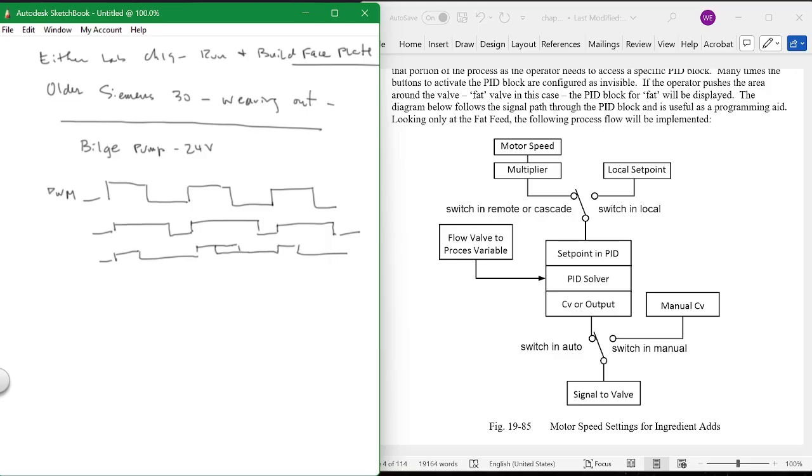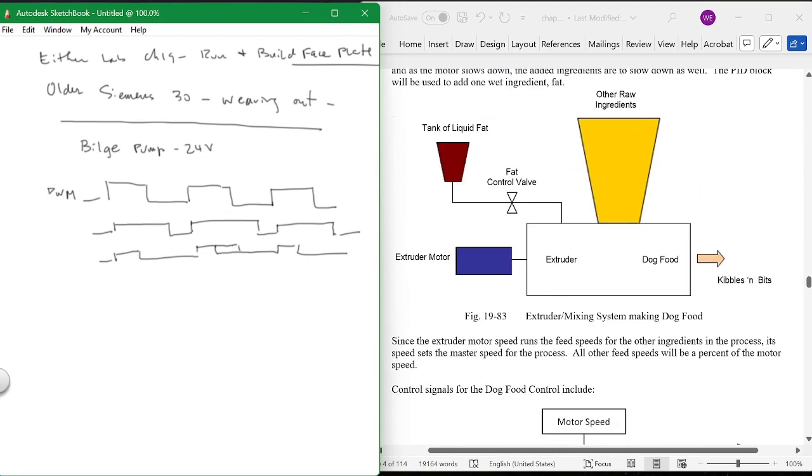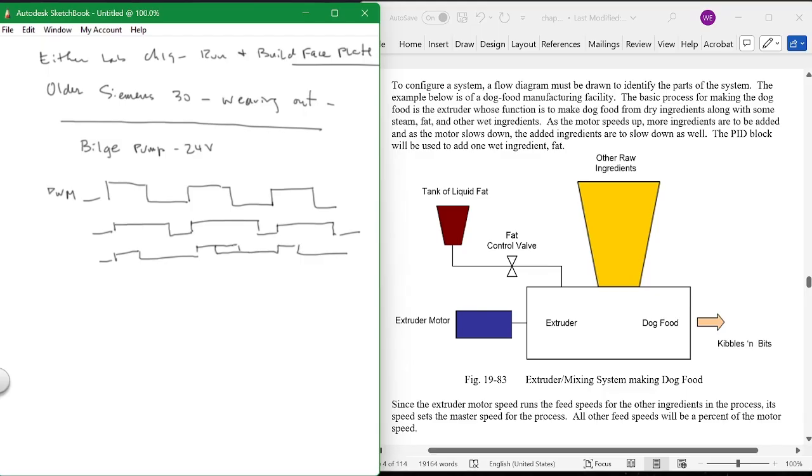Well, the case comes up that if I were to come back up here, and there was a rag that came down through this thing and plopped into this valve, what would happen to that valve? It would plug up, I guarantee you, okay? The old rag in the valve trick. So you would go to zero flow, or very close to zero flow. Now, what happens when that happens? If you stay in auto, what happens?